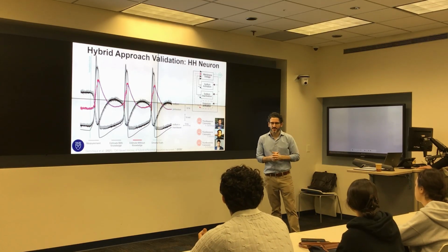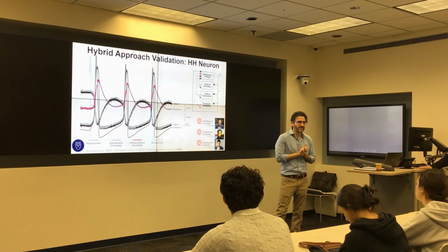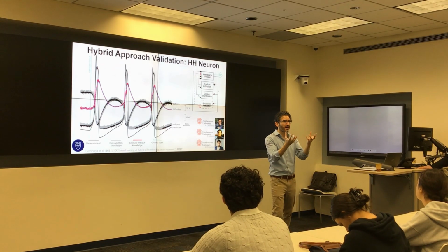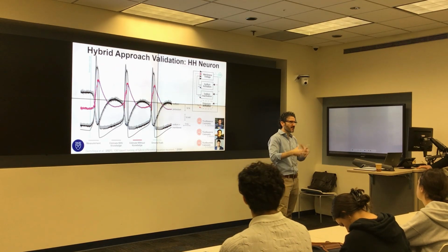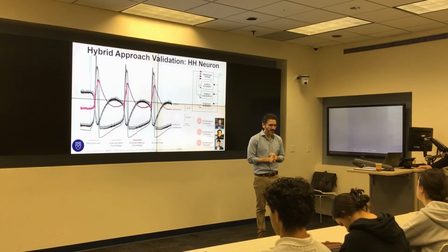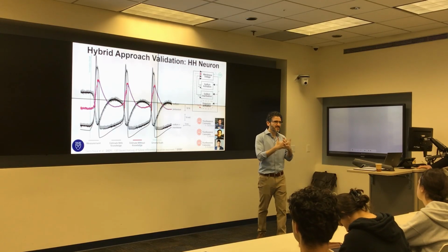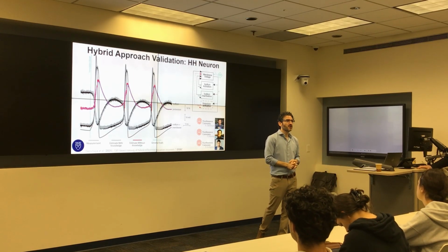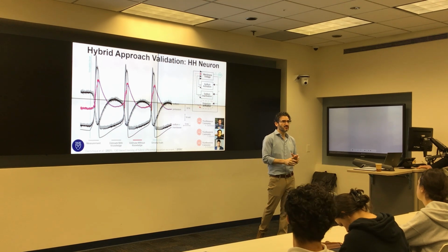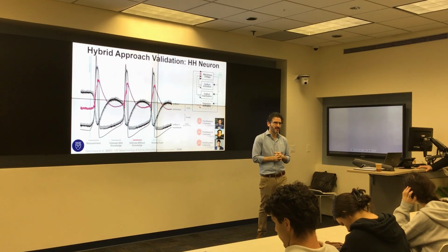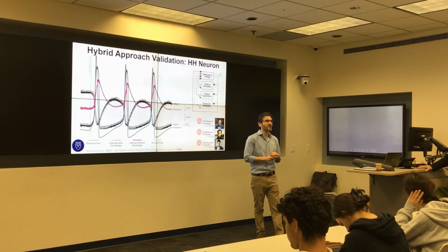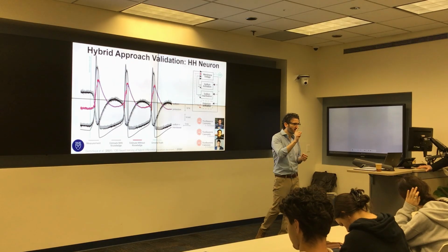So the excited student's question was about what your errors look like. It has to do with the innovation in the Kalman filter. For most of the states, most of the time, they look white. They look unbiased. You can't do better, or at least we don't see any structure in the residuals.